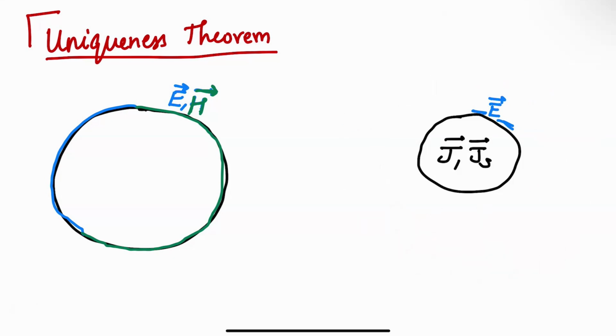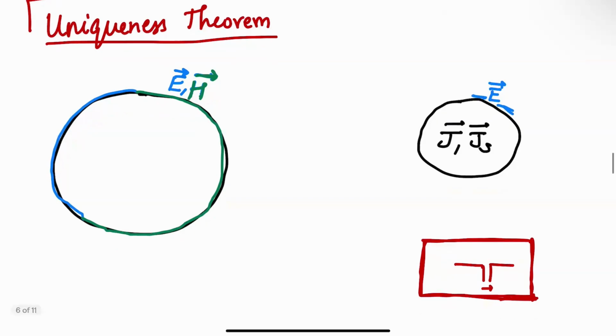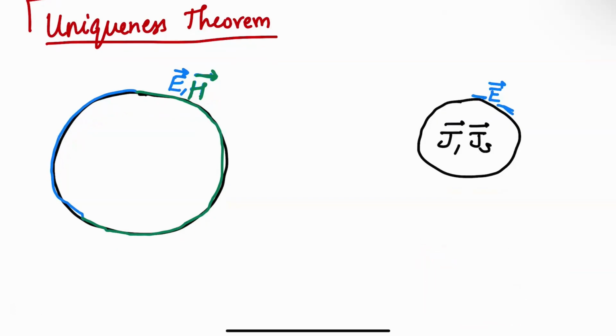Okay, so if you understand that, that's very nice because that's exactly what HFSS uses, right? You have an air box inside which you place your antenna and some port. We'll see this later. What HFSS does is it calculates the fields on this outer box, and then from that, it can calculate the far fields that you usually plot. And because the far fields are unique once you know what the fields on that surface, on that air box, are. That's the idea.